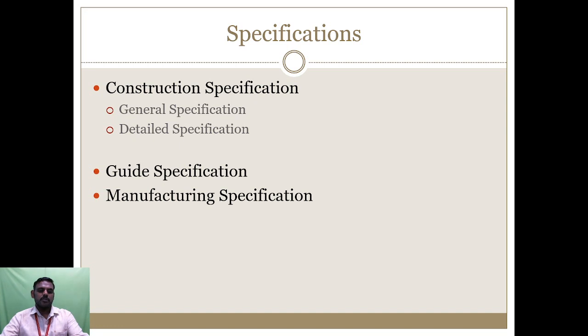If you plan to construct concrete, we have to choose the cement quality and which grade we are going to use, then the aggregate size, the aggregate shape, the fine aggregate level and grade, whether M sand, P sand or river sand.